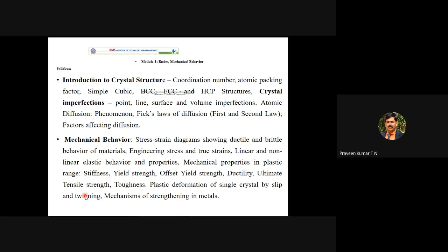By heating the material to the red hot condition, you have to beat it with the hammer. Finally, you have to reduce the cross section, or transform it from circular to a rectangular cross section. After hammering, it will always be a rectangular cross section only.